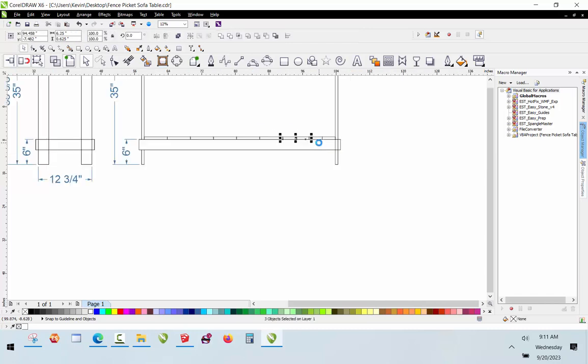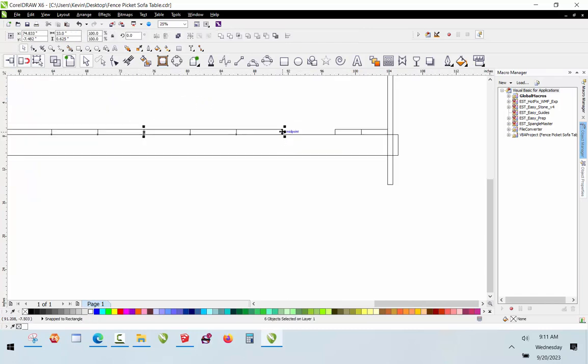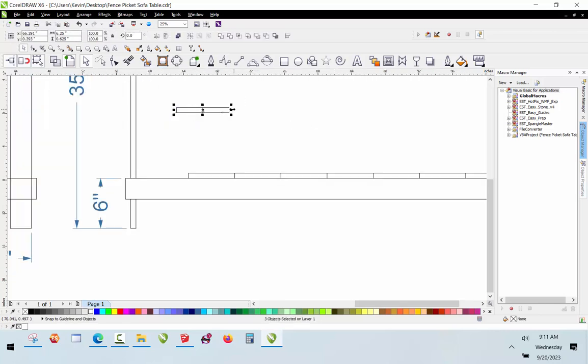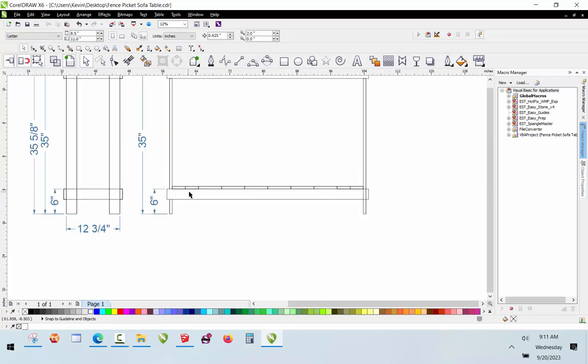And then on this end, down here, we're going to do the same thing. Okay, so we'll have 3 1/8, 3 1/8, and then all 5.5-inch boards. Because I don't really want to take the time to cut every single board going across there, so we're just going to do the 2 ends.